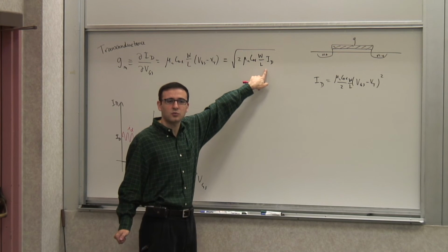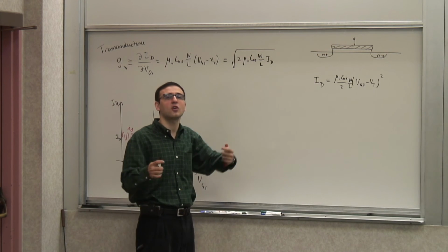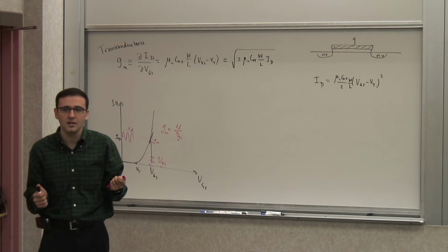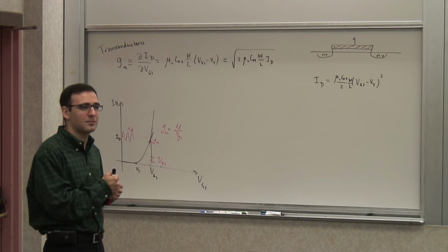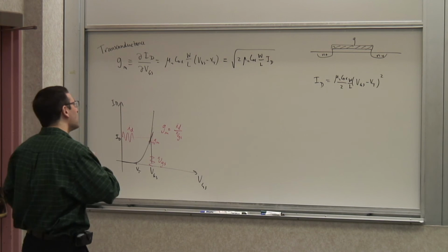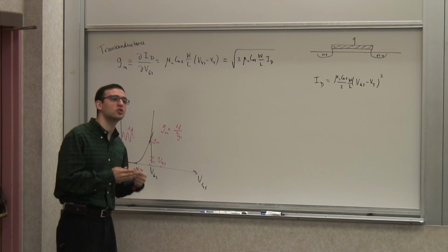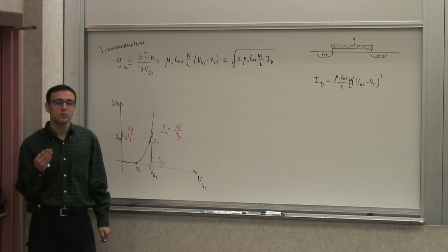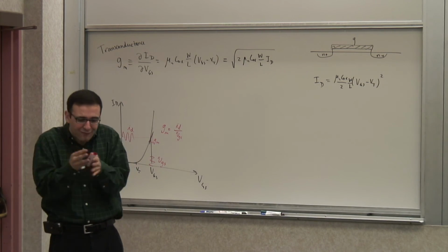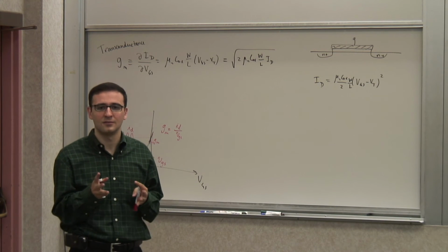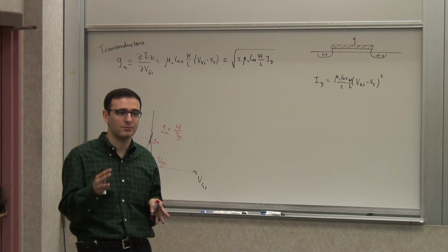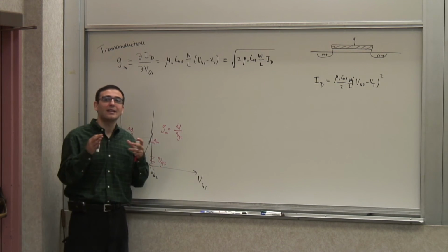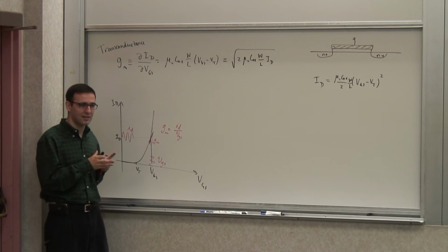So what does that mean? Which one is a better, a stronger device inherently? The BJT, because of that strong linear dependence. It has more drive capability. It can drive more current. And that's why, in the silicon domain, the fastest transistors are BJTs. Although MOSFETs are catching up quite fast, they are still not as fast as BJTs, and they don't have as much drive capability as BJTs.